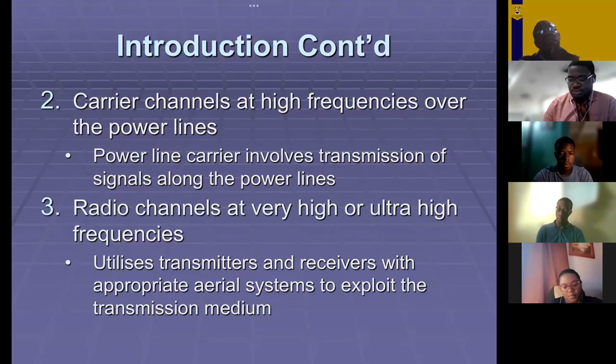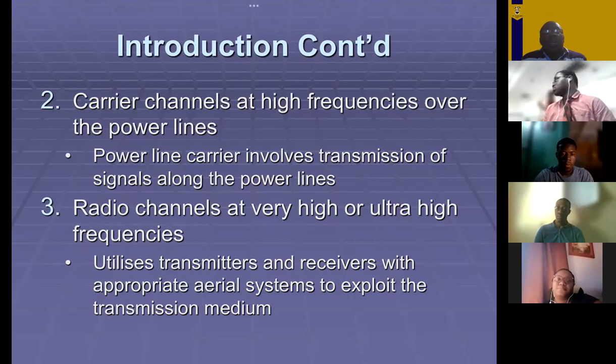Because if you have hills or mountainous areas between the two substations, you can't fully dictate where you place a substation. Whilst there will be ideal locations, you have to locate it based on the load center and the availability of property in the area.